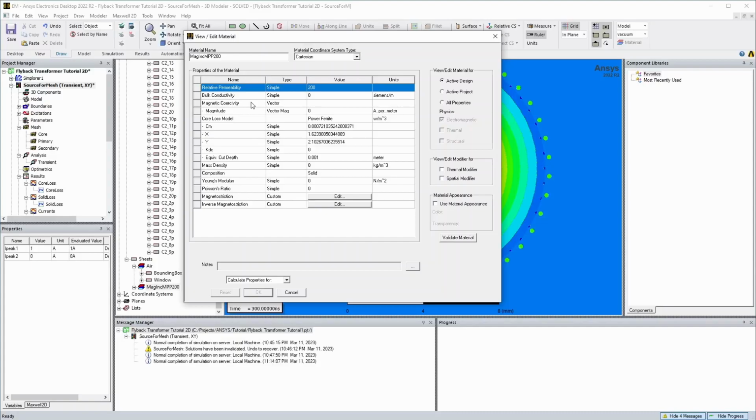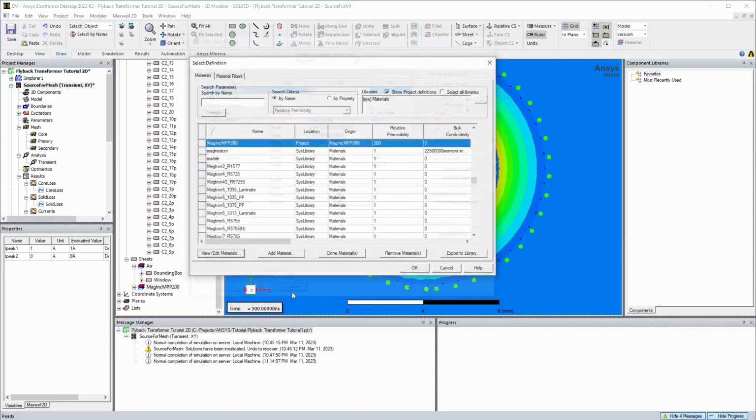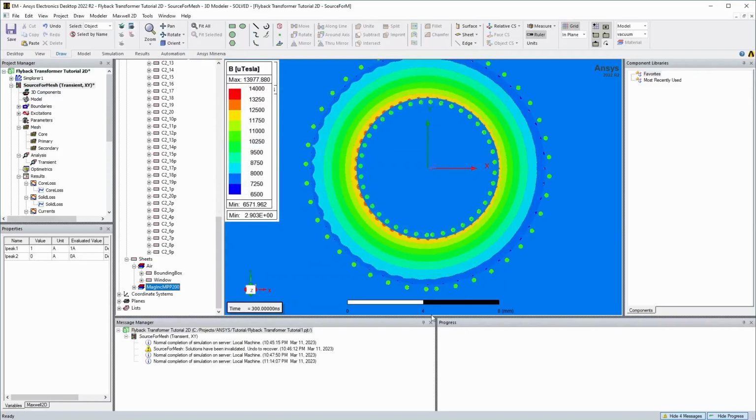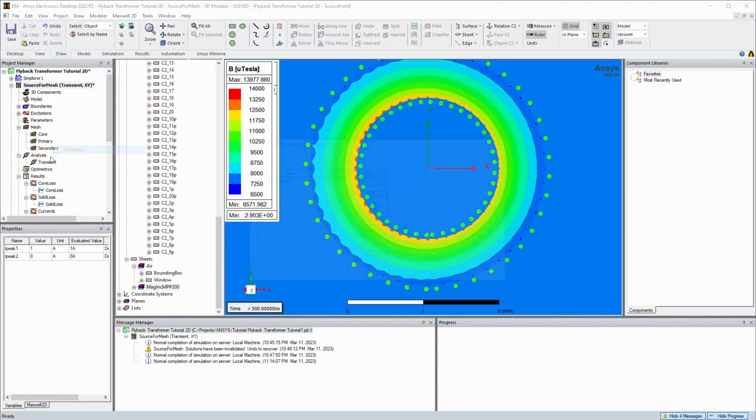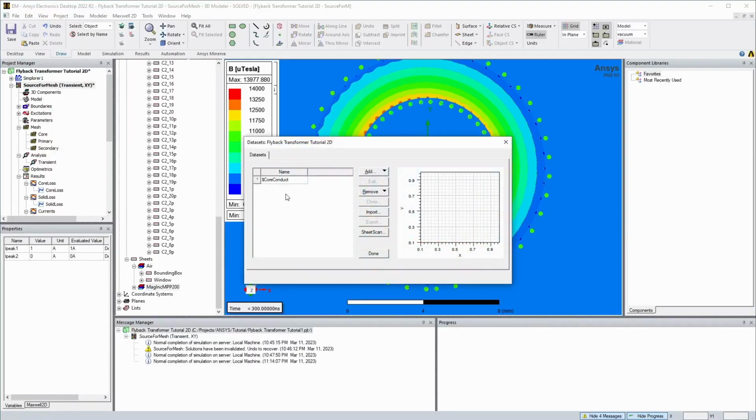So up here, if you try and give it a permeability as a formula up here, and then you have a data set, I was having problems with that. Sometimes it would work, and sometimes it would just hang with no errors. And that was because the data sets in here that was linked to it, I think maybe it didn't have enough range of points over enough frequencies or something like that. But you can play around with that. If it hangs, try disabling one of those.